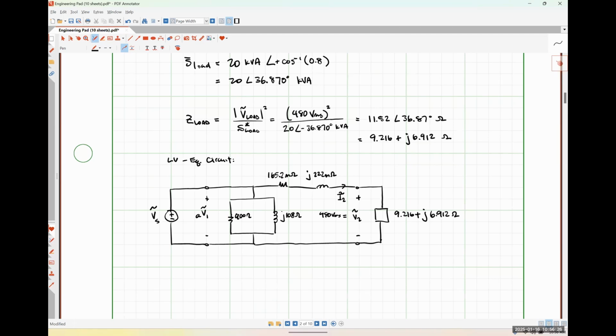So there are a couple of different ways that we can do this, but this is the reason why we use a cantilever equivalent circuit, okay? With a cantilever equivalent circuit, I have these guys that I can lump together as one impedance. And then I have this guy right here that is a single impedance. So I have just two impedances in series. I know the voltage drop over one of them. So can I use something like voltage division to find out what the total voltage across that series combination of impedances is? I think I can.